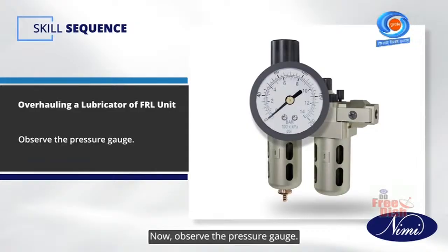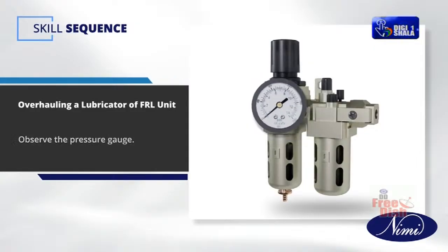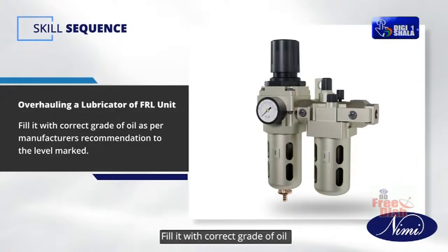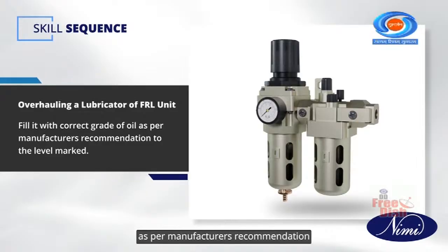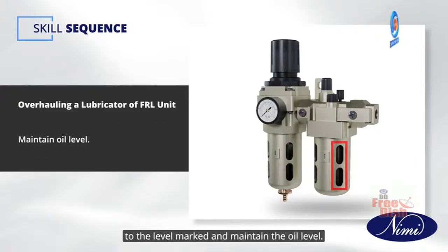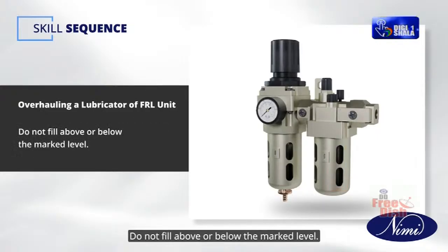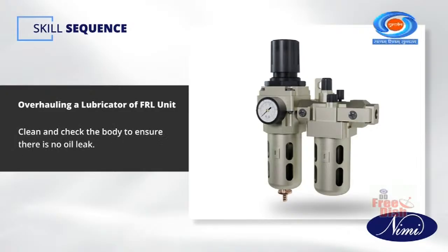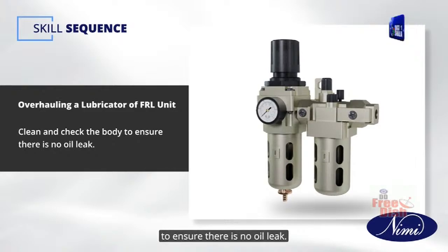Now observe the pressure gauge. Fill it with correct grade of oil as per manufacturer's recommendation to the level marked and maintain the oil level. Do not fill above or below the marked level. Clean and check the body to ensure there is no oil leak.